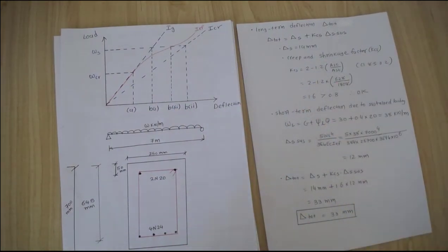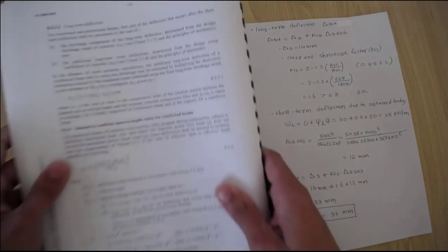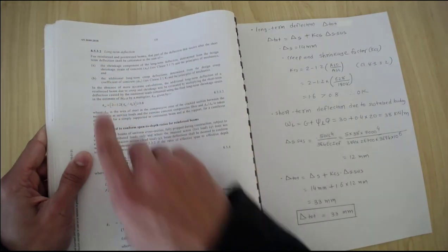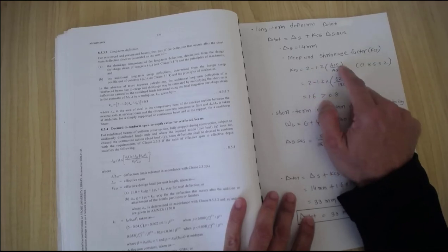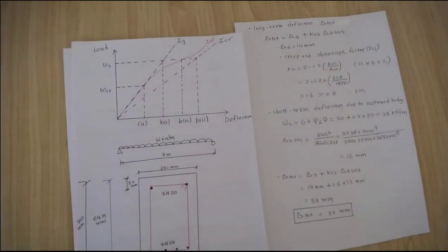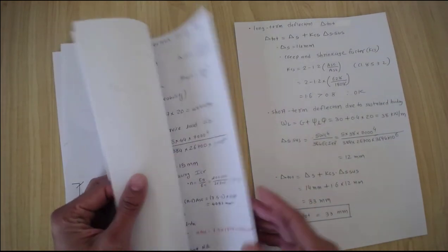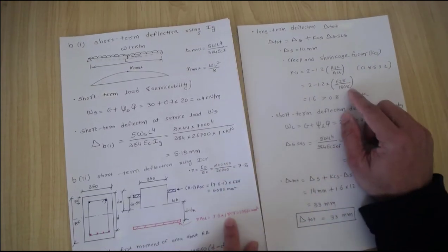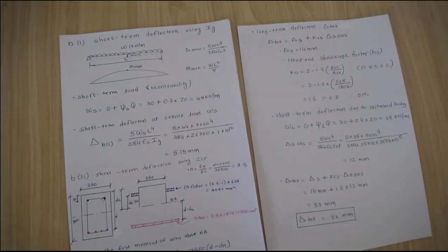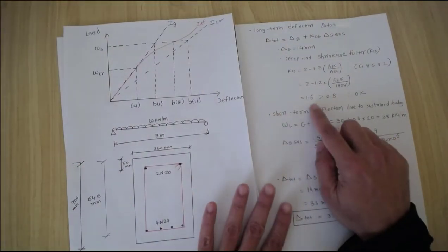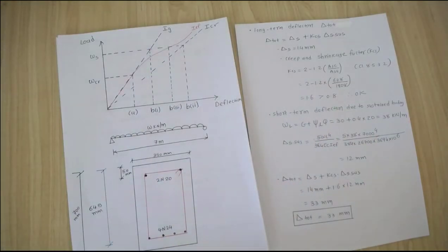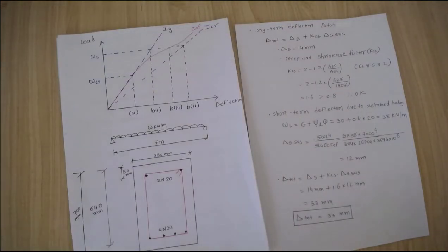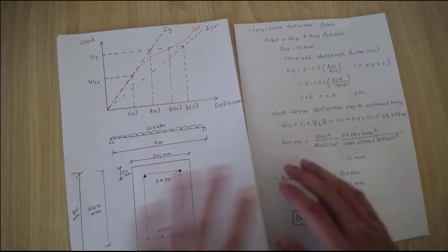For the creep and shrinkage factors, if you go back to the standards, on page number 130, clause 8.5.3.2, it has the creep and shrinkage KCS factor given here, which I copied: 1.2 minus ASC over AST. Now ASC stands for the compression reinforcement. Compression reinforcement we discussed is 628, tensile reinforcement 1808, that we discussed in the previous video, which I substitute. The simplification gives me 1.6, greater than 1.6. Now the standards also ask you to check whether this KCS is greater than 0.8. So we check it here. 1.6 is greater than 0.8, so therefore it's okay.